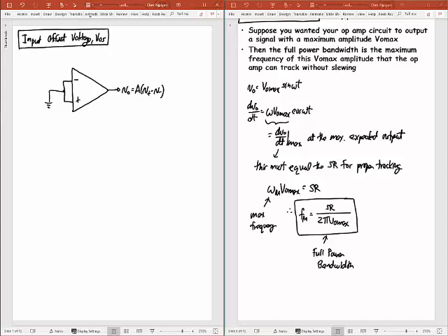Okay? And if this were an ideal op-amp, if I grounded both the plus and minus terminals, it doesn't matter what my gain is. Well, it shouldn't be infinite, but if it's a very large gain, then what I expect to have happen is that my output voltage is going to be 0 when I hook it up this way. Okay, that's the ideal case.